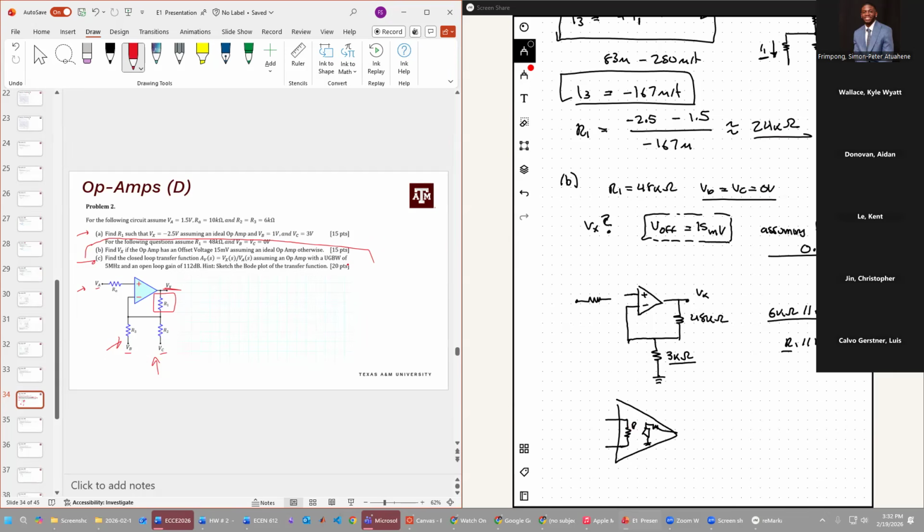where you have this internal resistance which is huge, like you want it to be a really large value, that way there's very little current flowing in. But on top of that, there is a slight offset voltage mismatch which appears on the op amp. And often the way we model it in problems is something like this, VP is equal to V offset plus VN, right?